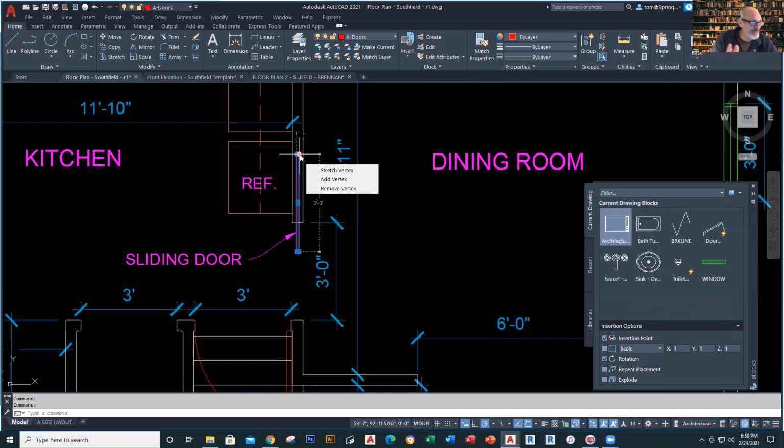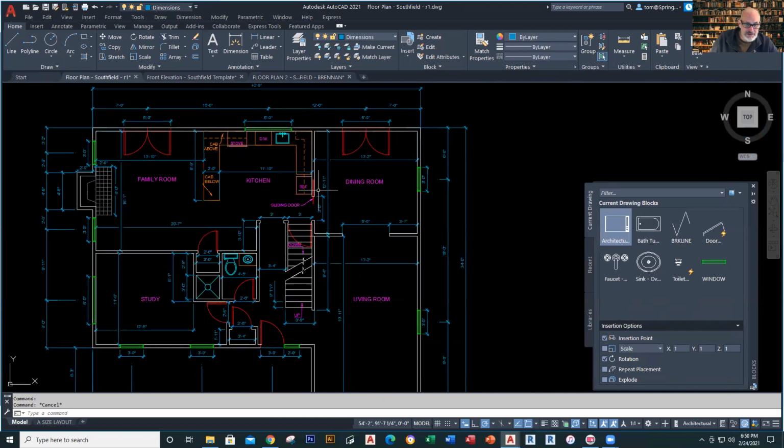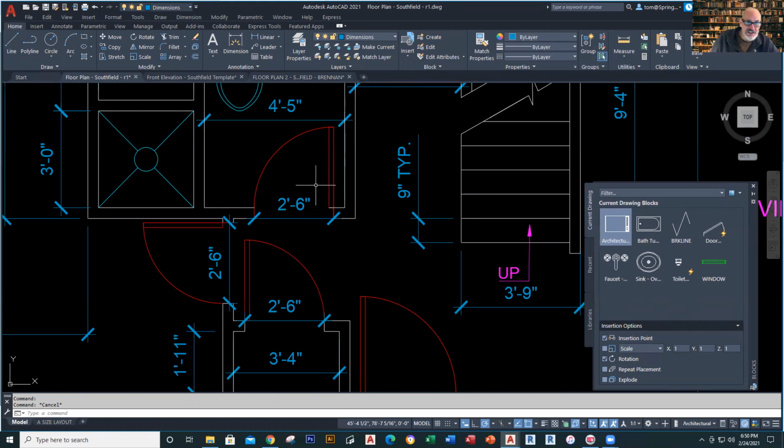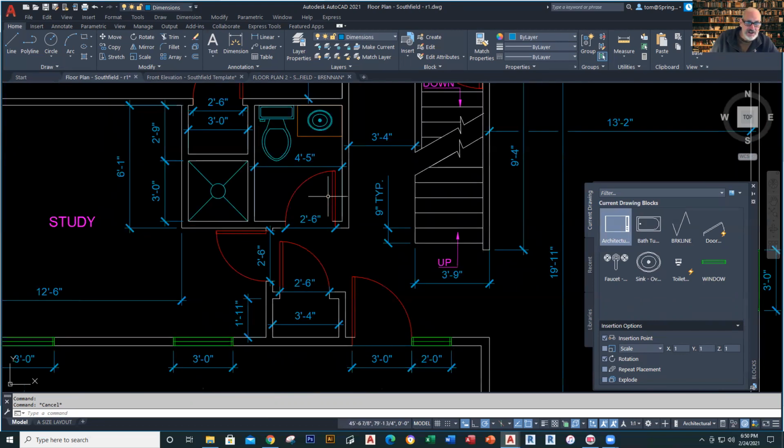That's how long that slab is, just a little slab door that fits inside the wall. So that's a 3 foot by 1 inch item right there. And then right here, for instance, I've got this. If I did not give you an actual distance or an opening, usually 4 inches off the inside door is acceptable. So for this, I didn't give you a dimension, so 4 inches off of the wall will work out quite well. And that's how you can place these doors.